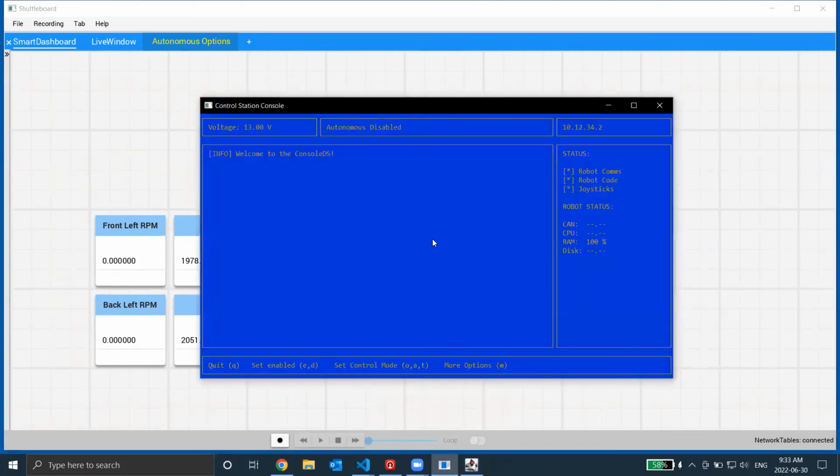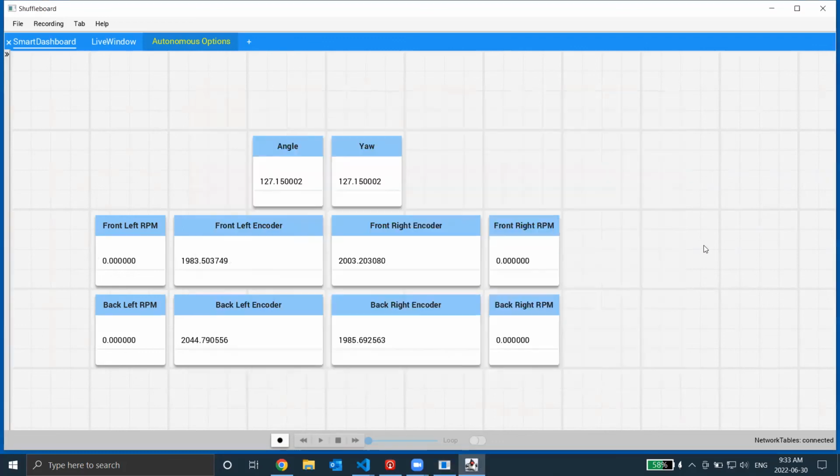Now, Derek reset it back to the spot just so that we can show, can we repeat that? So if I hit enable again, you can see it drove again. And our values are still the same or similar. So we could calibrate that, redo the PID so that's more tolerant to what we want.